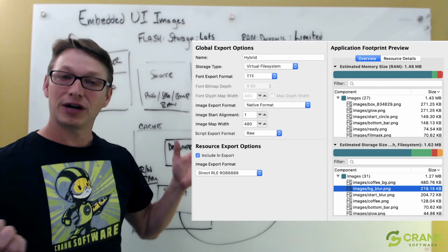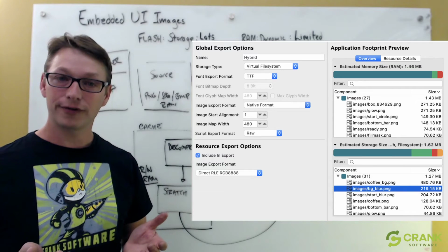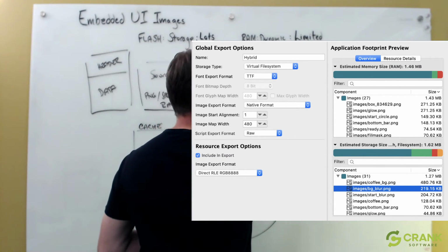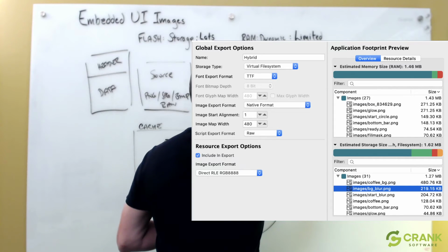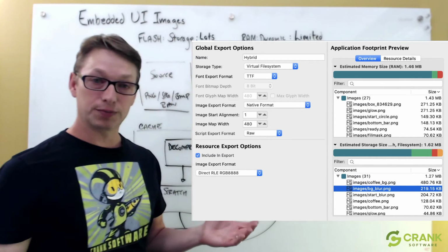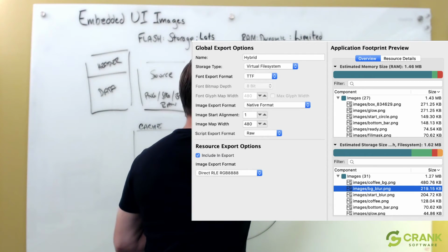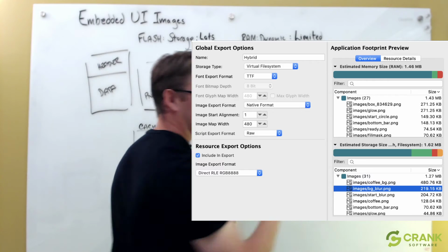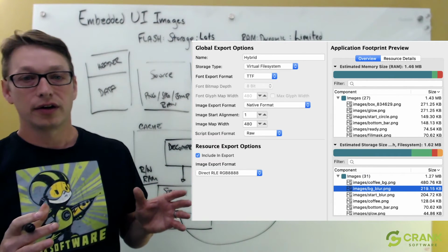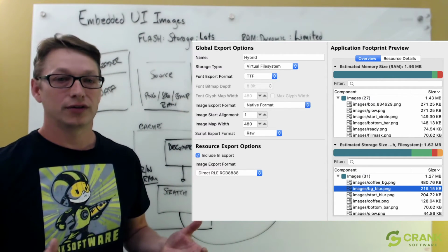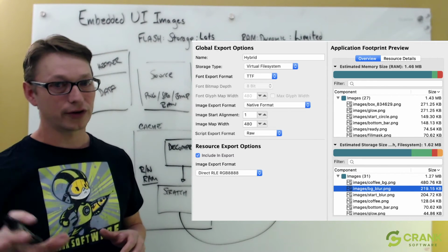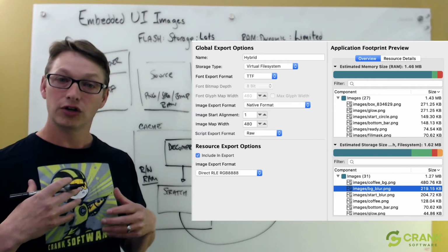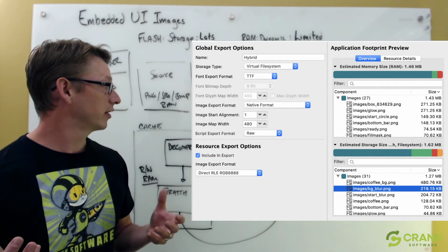So frame buffers are probably the easiest. Your frame buffer requirements are likely going to be summarized as the width and the height of your display multiplied by your color bit depth. And here I'm assuming a scenario where we're doing direct draw. We're not palette-based. We'll have a whole other session when we talk about palette-based images and palette-based displays and what the benefits and drawbacks are there.